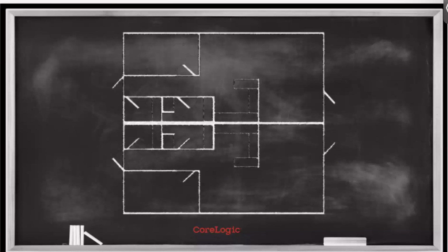But this time, instead of doing a cross section on a schematic, let's do a top-down view on a schematic here and apply the same concept. So again, I'll establish a wet area here. Let's draw out an area of migration. Let's say that this is my area of migration and everything inside of this area is wet. All right, let's start talking a little bit about drying chambers. Let's say my dehumidifier is installed here, just to start the first part of this drying chamber conversation. And now let's establish some air movement.